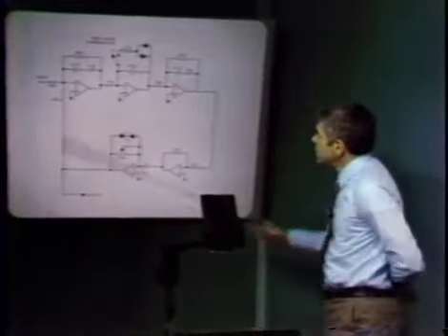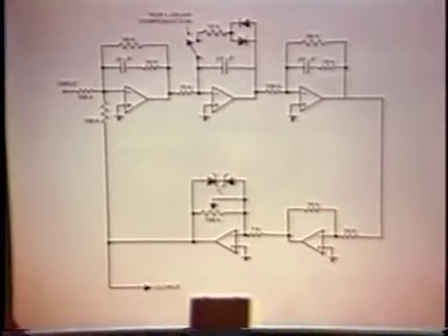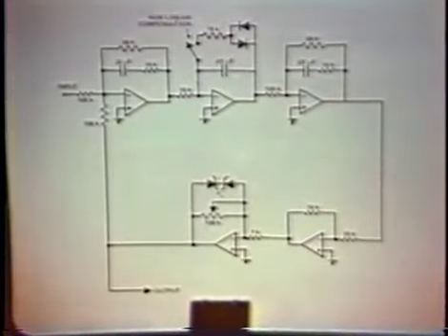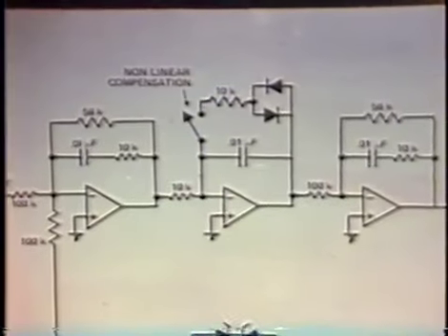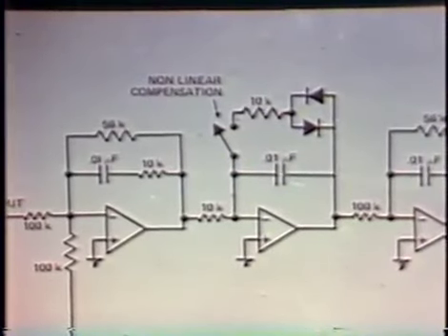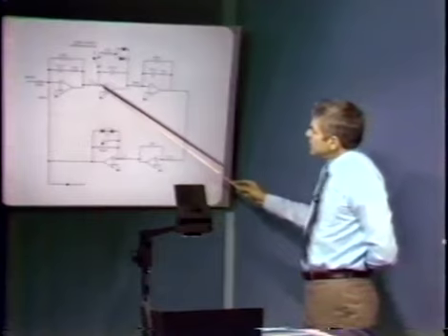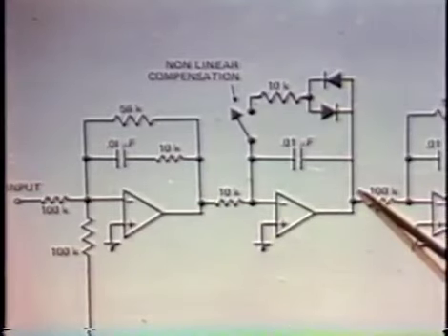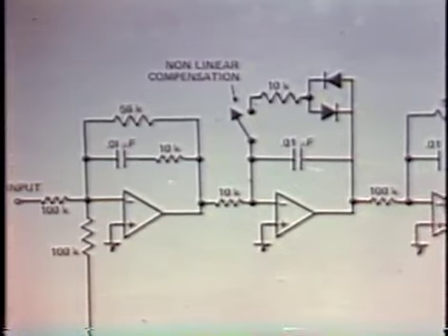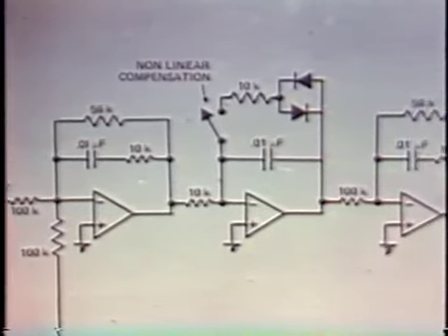and look at the point that I glossed over that says nonlinear compensation. What you do, I think, or at least one technique for compensating this sort of system, is to consider what happens if we keep track of signal levels. We find that when the system is behaving normally, at least in the high gain configuration, we normally want to cross over in this system above 950 hertz. When the system is behaving in that manner, the signal level here is very, very small. If you keep track of the maximum signal at this point, we found that it's about 6 volts.